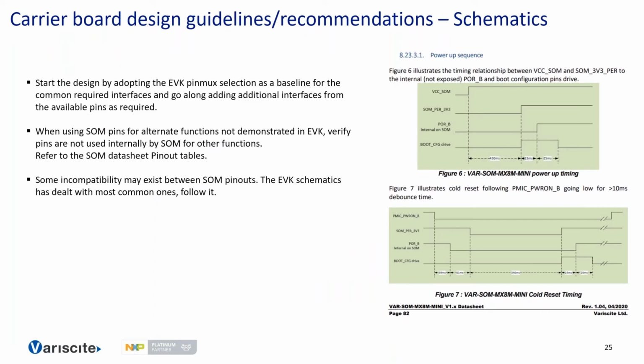So, a few guidelines when coming to design your board. Since we made an effort to maximize the number of compatible interfaces across this family, I suggest you start by adopting the EVK pinmux selection as a baseline and add interfaces which are missing according to available pins. Now, if you need some interfaces which are not exported, you should verify that these pins are always available and not used by the SOM for other functions, and are not dependent on certain SOM assemblies. You can find the exact details in the datasheet or in the spreadsheet.